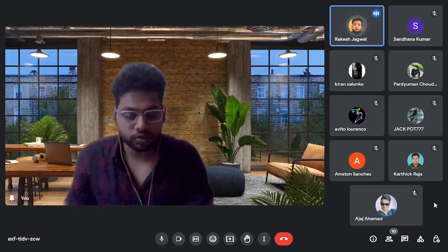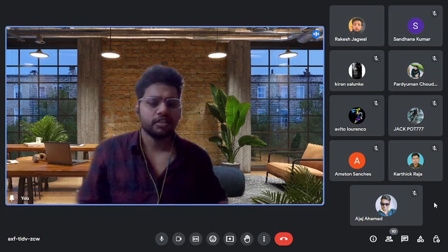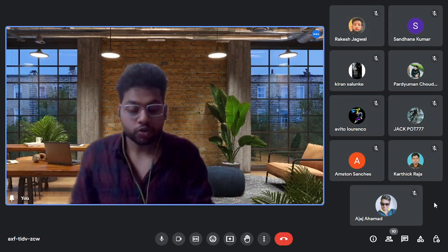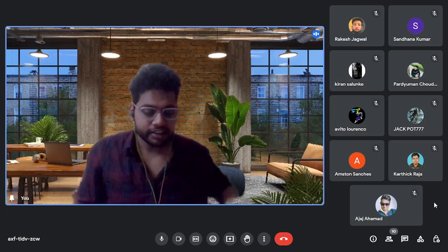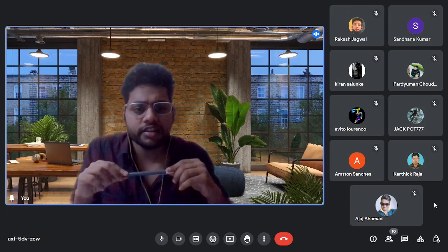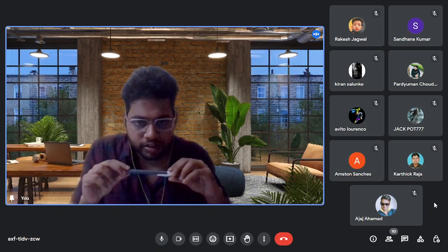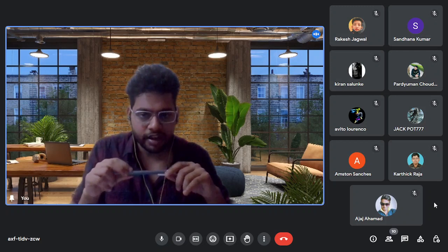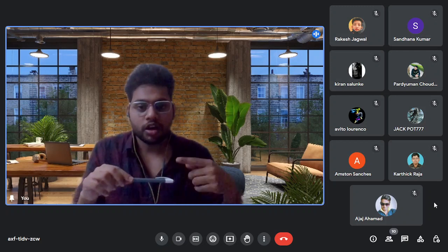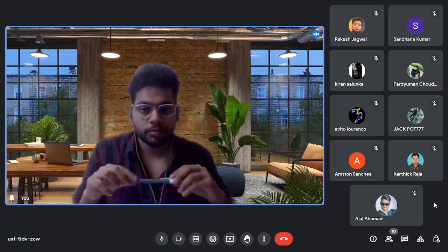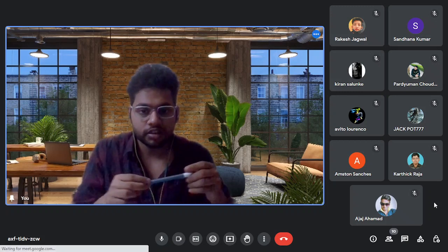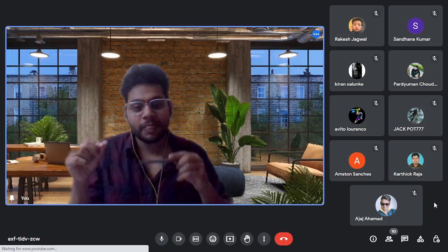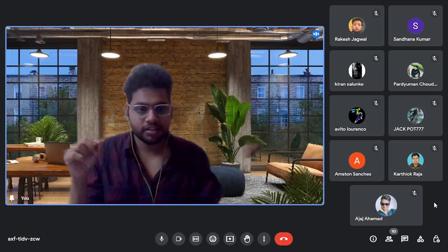Sinusoidal wave. Pulsating flow is DC, that is a single flow direction. That is the sinusoidal waveform. So the reason in AC is the rotating magnetic field, like in an AC generator in which the rotor is rotating, so the magnetic field is rotating, and in the stator there is an armature winding where current is induced. Because of that rotation in the magnetic field, the AC current is induced, and because of that the AC current direction is changing.